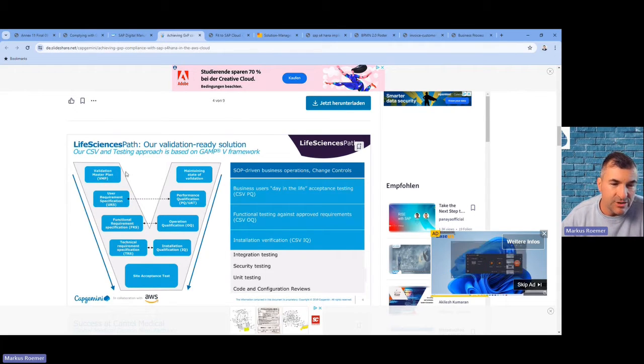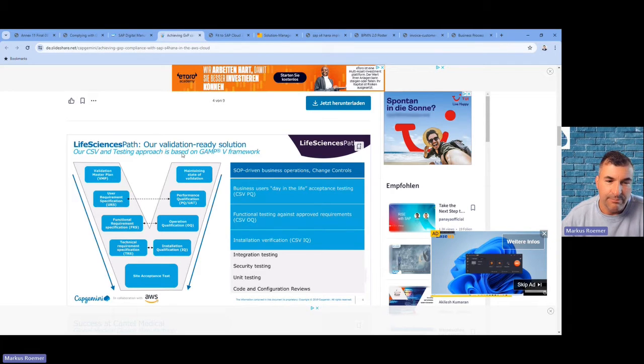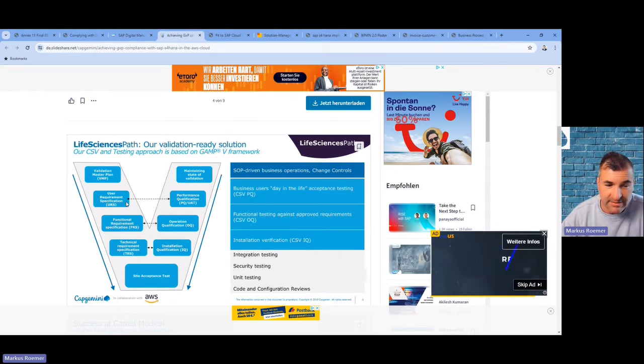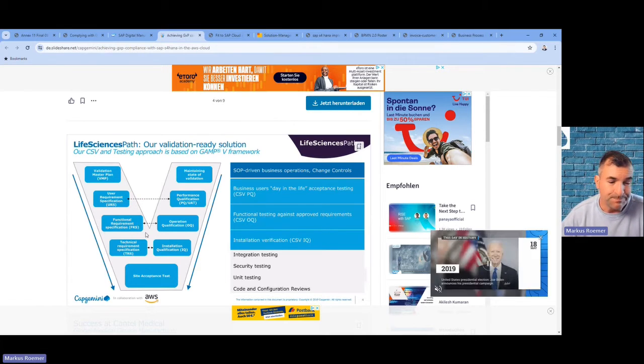So it started with a validation master plan. A validation master plan is an overall document, or could be an overall document. So they mean a validation plan. They write approaches based on GAMP 5 framework, which is totally not true for any of this. User requirements specification now is specifying requirements. FRS never existed. It was functional specification. It was replaced 1.5 years ago.